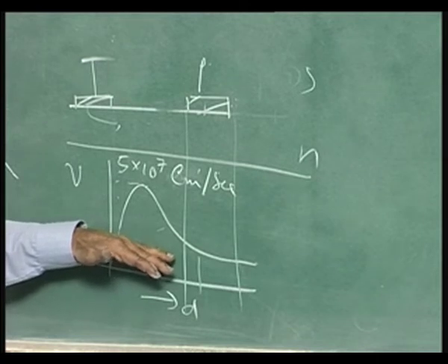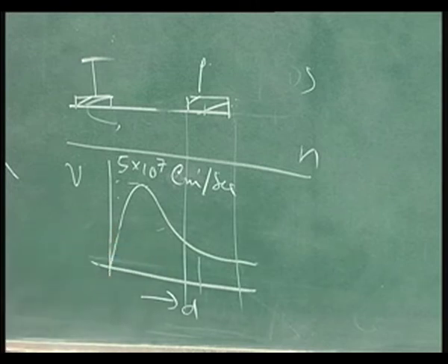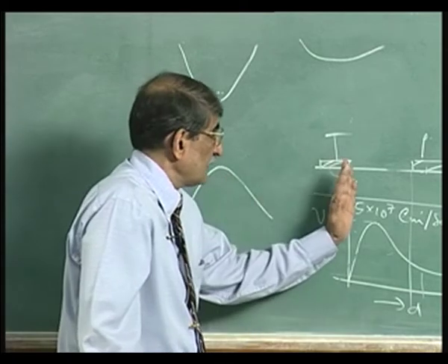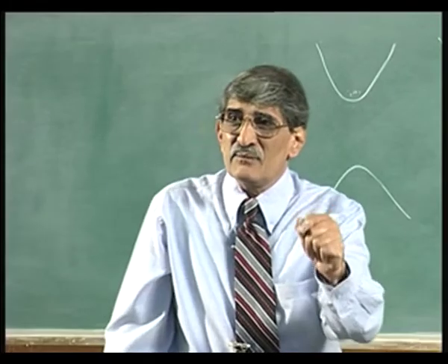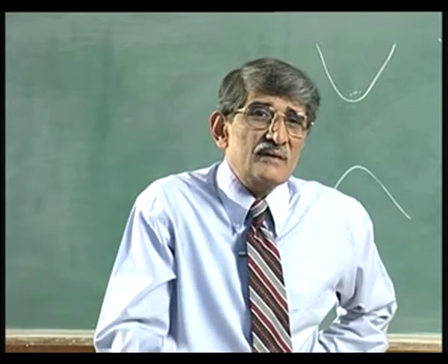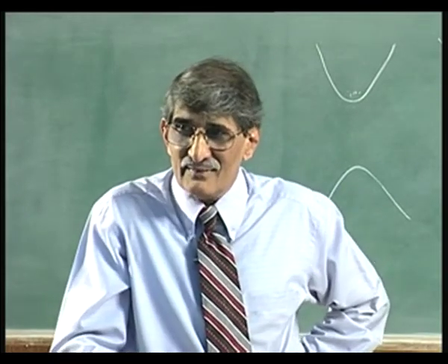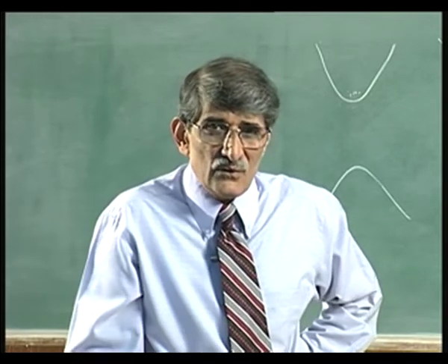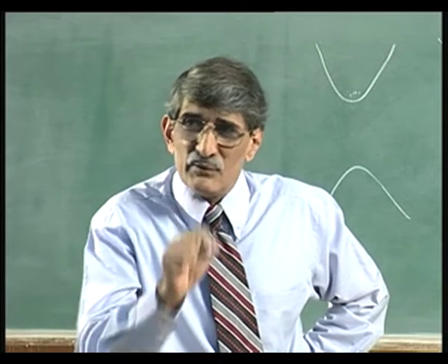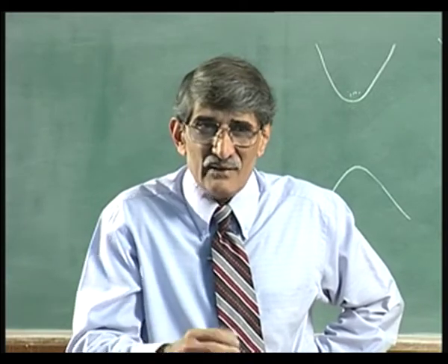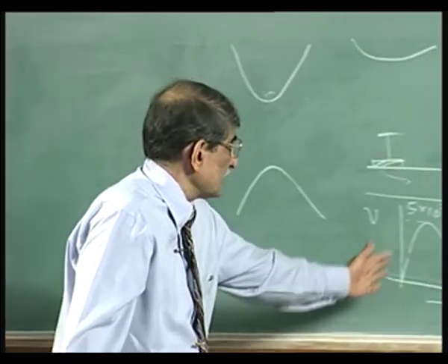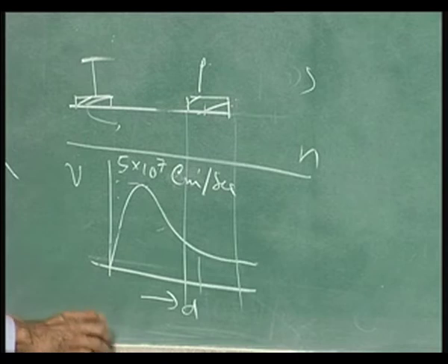This is the reason why you get transconductance with gallium arsenide which is much higher than that of silicon, even when the channel lengths are shorter. Okay? Now, the only condition that you must have is where you get the gate control, that is the point at which the electrons must be injected. After all, you should be able to control the current. The real channel is the gate region. So, you must launch electrons right into the mouth of this gate, the source end of the gate, so that from there it gets accelerated like that. Okay. So, is that clear enough?